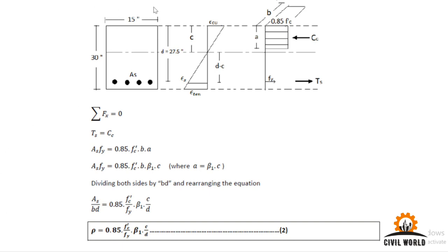Okay, so we have the given beam which is having section as given, and now your compression strain in concrete has reached its ultimate limit. It means it will fail at this strain, which we discussed in our previous lecture, and the value for this strain is 0.003 as per ACI code. We have some strain in steel. Concrete has already cracked. There are some stresses in steel, and at failure point, we'll assume that it has reached its yielding stress.